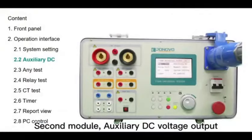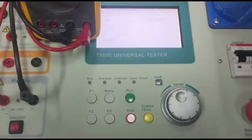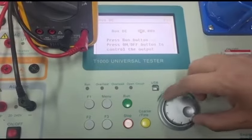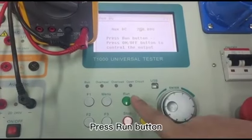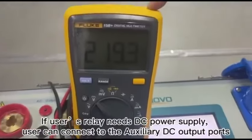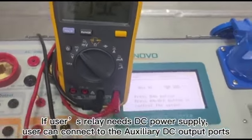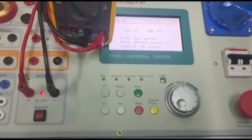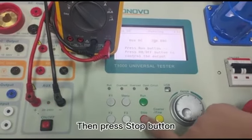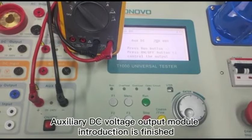Second module, auxiliary DC voltage output. Here we output DC 220 volts. Press run button. Press on button to output. If user's relay needs DC power supply, user can connect to the auxiliary DC output ports. Press off button to stop output. Then press stop button. Auxiliary DC voltage output module introduction is finished.